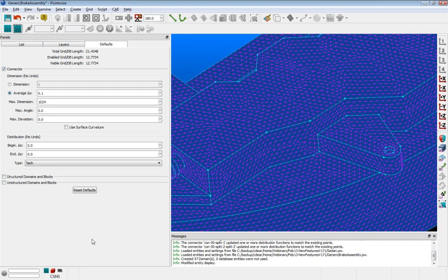As you can see, we still have nice equilateral triangles on our surface mesh. However, the behavior is a little bit different. With an advancing front technique, it creates these equilateral triangles and grows them off the boundary. So in other words, you're going to have layers of equilateral triangles off each of the boundaries. Now, as you can tell, it's a very pretty mesh. It's very pleasing to the eye, and it looks very structured and very regular.